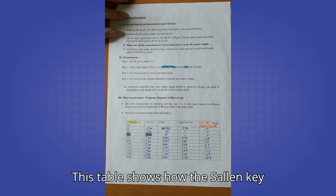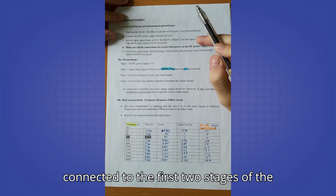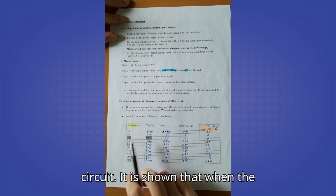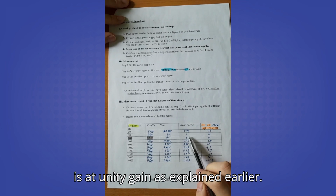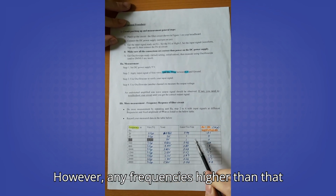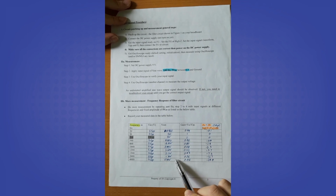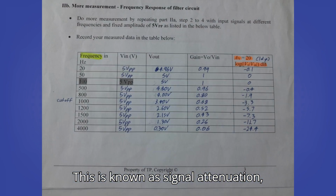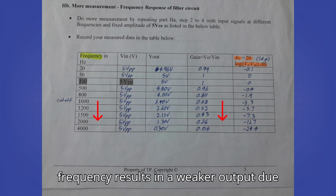This table shows how the Sallen-Key operates by itself, whereby it is not connected to the first two stages of the circuit. It is shown that when the frequency is below 500 Hz, the filter is at unity gain, as explained earlier. However, any frequencies higher than that results in the gain and output voltage dropping. This is known as signal attenuation, whereby any frequencies after the cutoff frequency results in a weaker output due to a smaller voltage gain.